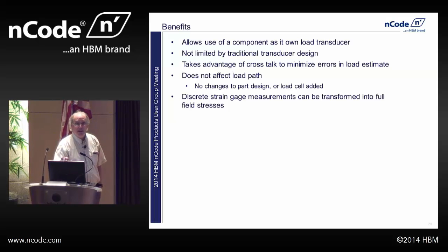And then as a benefit, if I take this approach and I have several discrete strain measurements on a component that I can use to calculate the actual loads, I can take those loads back into DesignLife, and now I have a full field stress history. I can look at the entire component in terms of fatigue.